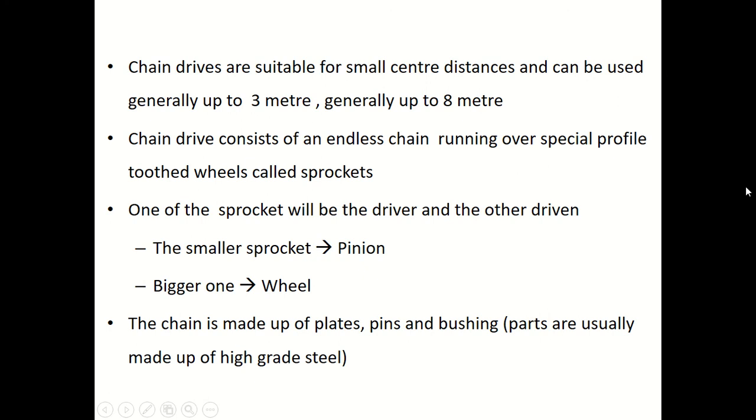The chain drives are more suitable for small center to center distances and can be used generally up to 3 meter. Okay, so that is the chain drive. Usually this chain drive consists of an endless chain running over special profile.